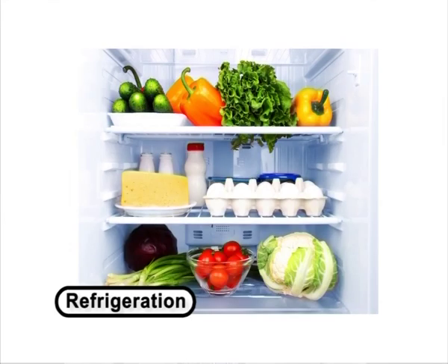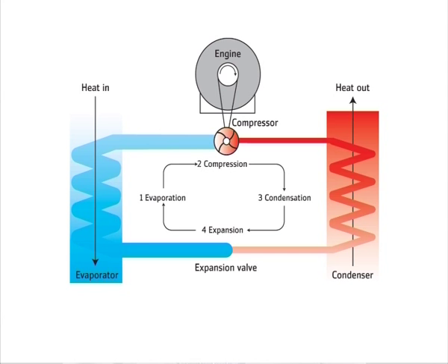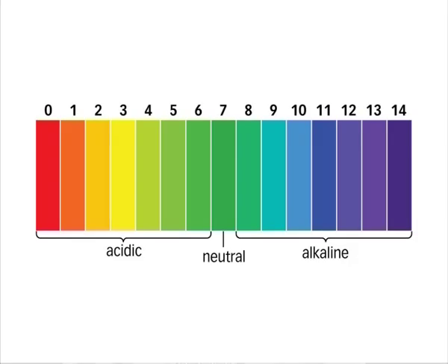Refrigeration could be achieved by melting a solid, sublimation of a solid, or evaporation of a liquid. In a simple vapor compression cycle, compression, condensation, expansion, and vaporization are completed. To represent the steps thermodynamically relating to the state of refrigerant, the p-h chart is used. The p-h chart gives directly the changes in enthalpy and pressure during evaporation, compression, condensation, and expansion processes for thermodynamic analysis, which is important to consider while designing a refrigeration system.